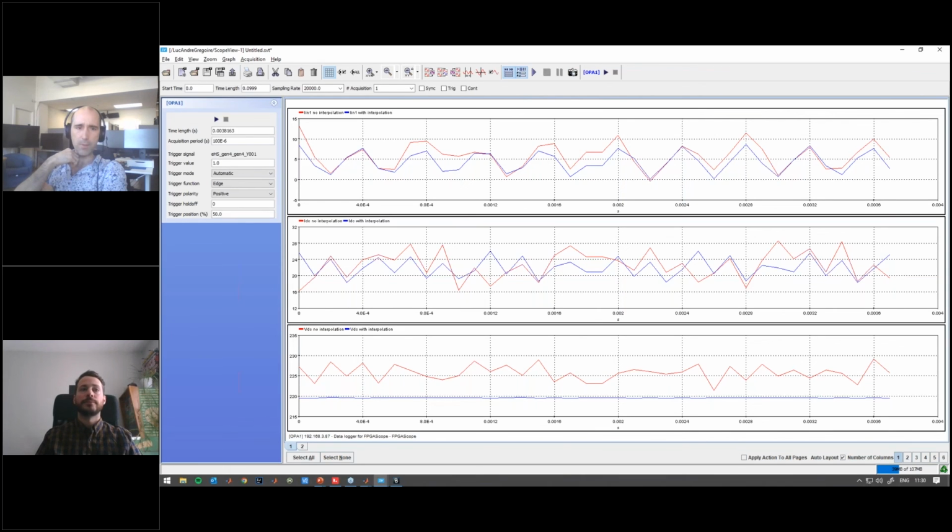Usually on FPGA, it's going to be under 50 kilohertz. Otherwise, you won't have enough points, and you're going to have aliasing again. And on EHS right now, depending on the topology, we can go to 200 or 300 kilohertz.